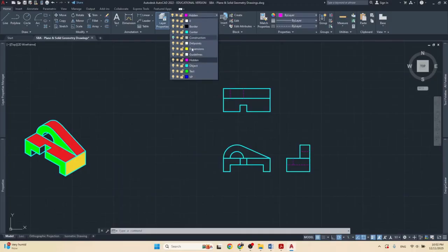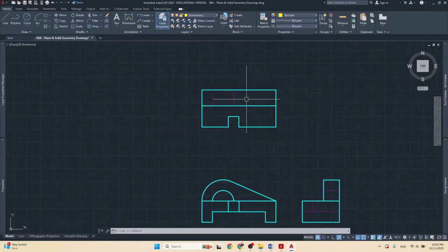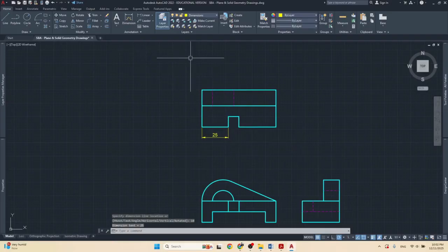So some rules about dimensions that you want to keep in mind. We can do two types of dimensioning in technical drawing. We can do chain dimension, which is basically this. If I dimension from here to here, 10 millimeters from the object, and then I continue chaining my dimensions onto the object like so. That's 10 and that's 35, right? I can do that. That's chain dimension.